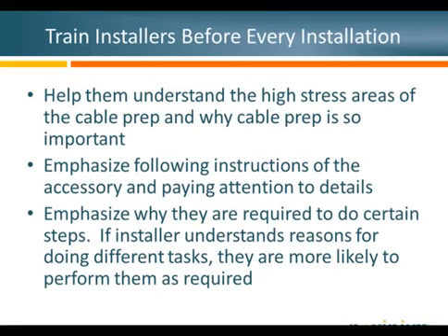And you want to do a lot of training, because there are tricks in order to install all different accessories and to make sure that they're installed properly. But in addition to the training on that, you want to emphasize the theoretical aspect of it, so they understand where the high stress areas are, and why cable prep is so important there to keep it from failing.